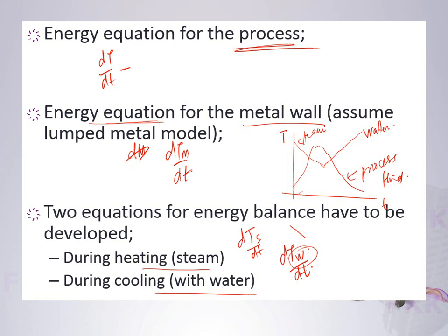The steam will cool off a little bit until it becomes condensed, because it is in touch with something cold at the beginning. When you start off the reaction, it goes in at 25 degrees Celsius, and after that you increase the temperature so that the reaction can proceed. The reaction has to proceed at a certain temperature range. After that, when the exothermic process is going like crazy, you have to maintain that temperature. When it's about time to collect your product, you have to pump in more cooling water, quench the process so that it will gradually decrease.